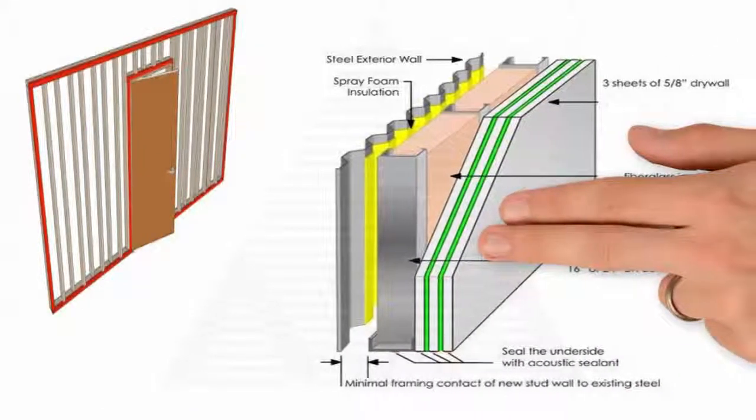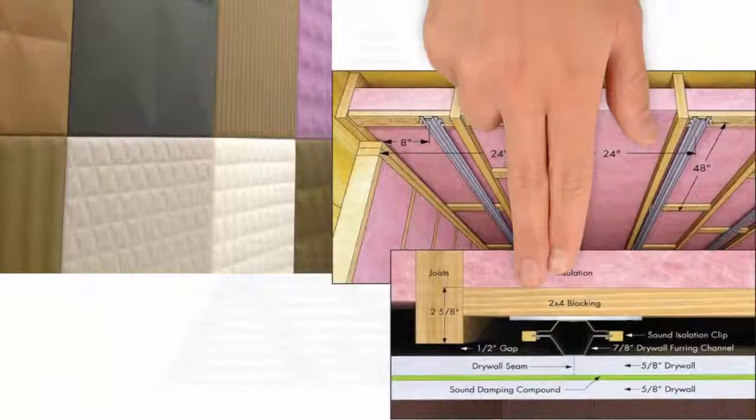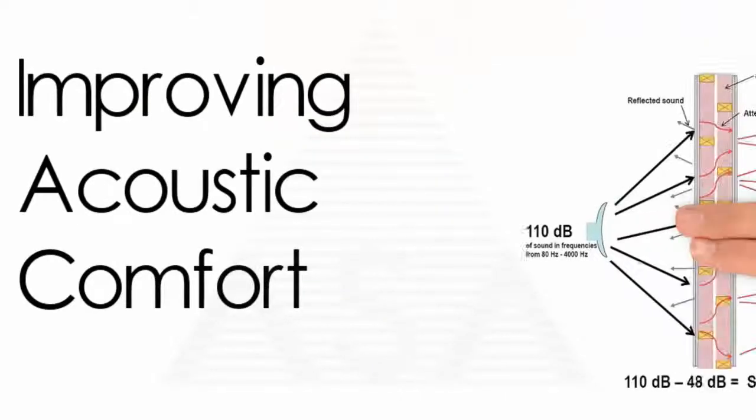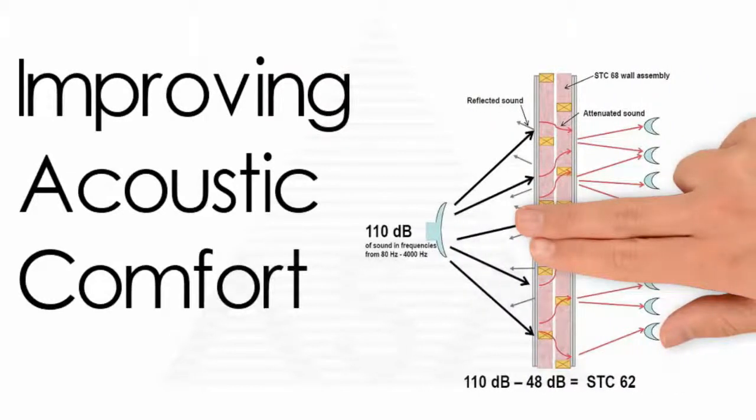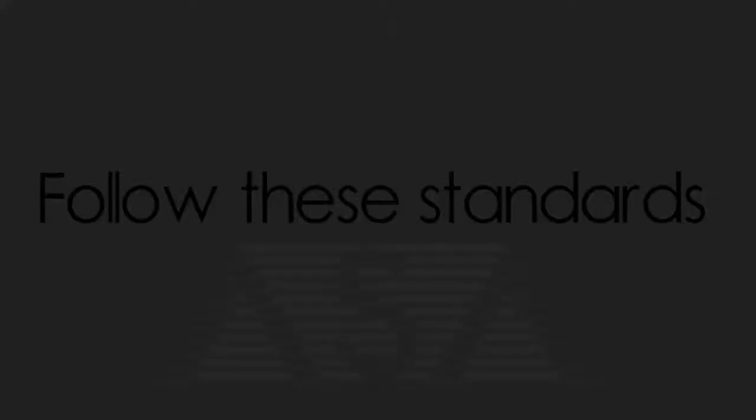Use of inexpensive resilient layers like glass or fiberboard, using different thickness and materials for panels. Isolation blankets placed in the airspace arrangement provided between the panels help in improving acoustic comfort. For reducing air gaps and limiting sound transmission, follow these standards.